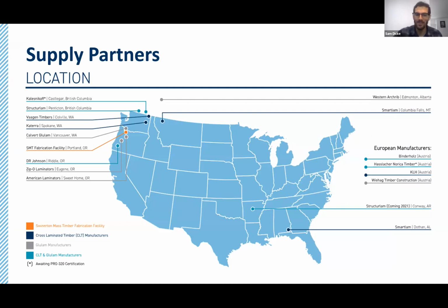Erica, you want to talk a little bit about supply for the project? Yeah. So I think the first thing to mention for this project is that we had the luxury of utilizing type 3B construction, and that really benefits us for our mass timber design because it allows us to utilize a 3-ply CLT panel. And as many of you might know, the driving factor in the cost of a mass timber structure is the total volume of wood fiber in the building, and the largest amount of wood is in that CLT deck. So as much as we can, we want to seize opportunities to reduce the thickness of the CLT panel. And whenever we don't have any fire rating requirements for our structure, as in the case of this Oregon State project, we look to using a thin 3-ply panel.